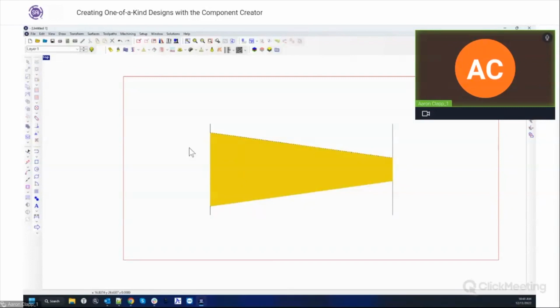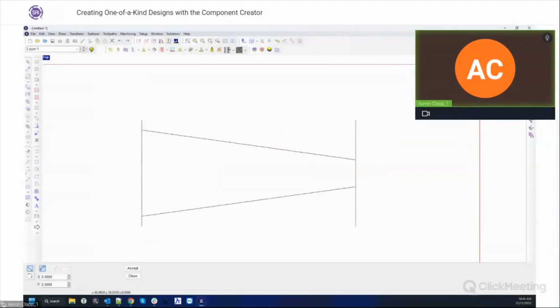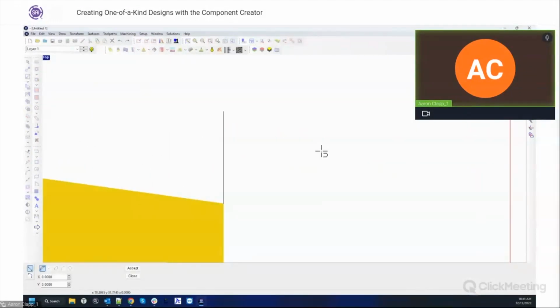Okay, now with sweep to rails, we have to have a profile that we want to apply to this, right? Obviously we want that slanted. So let's just create ourselves a profile. So here's what we're going to do. We're going to go like this, and we're going to draw some lines, and let me snap to the endpoint. Okay, and then let me draw a line here. Oops, not the shift button. There we go. Now I hit shift. Okay, and let's click a line there.